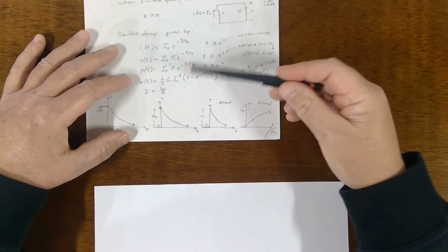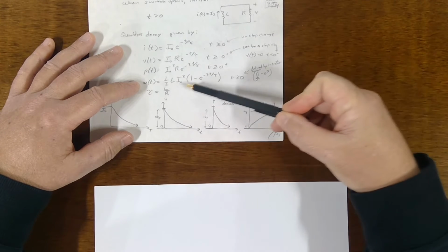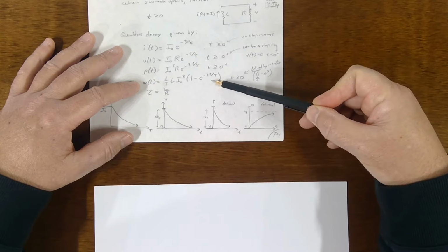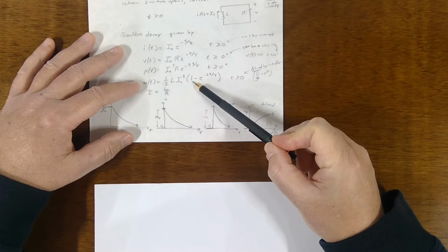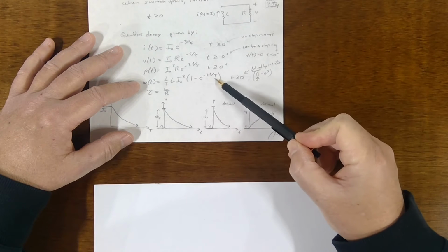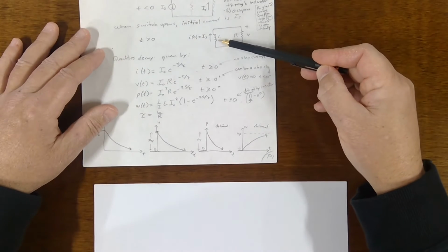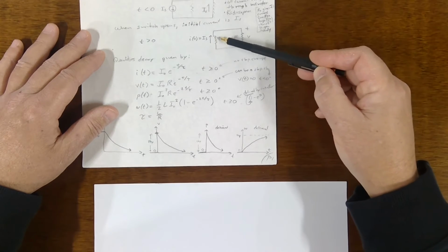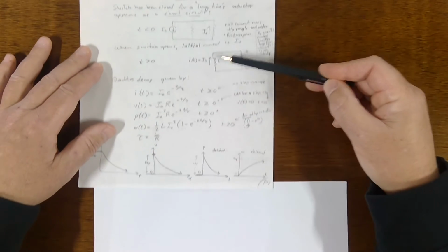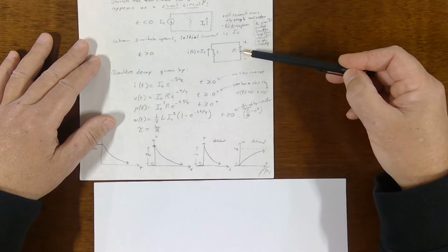Then the energy, we're using our general formula here, 1/2 L i squared, but because I is a function of time, there's this in here. Now this is from the perspective of the energy delivered. So in this circuit for t greater than 0, this thing gets charged up to an initial state by the left-hand side of this thing, and then it delivers its energy to this.